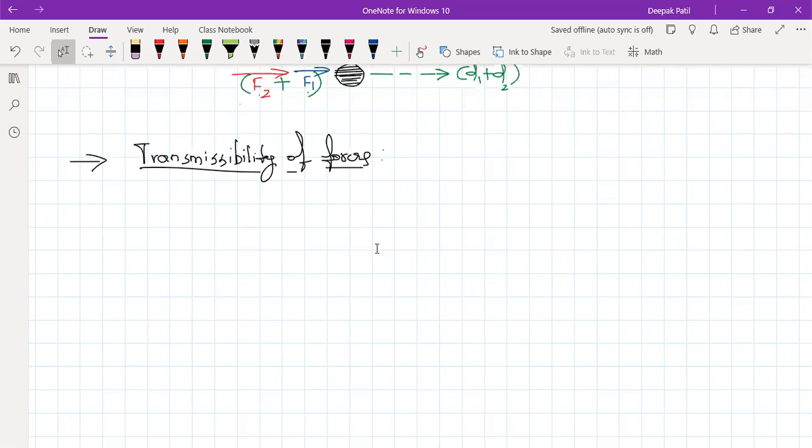along its line of action without changing the external reaction force on a rigid body, right? Any force that has some magnitude and direction and which has a point of application somewhere along the same line of action will cause the same effect. Therefore, the points of application of force may be moved along the line of action to simplify the analysis on a rigid body. Okay, I know most of you have not understood what I told. Let me explain that with an example.